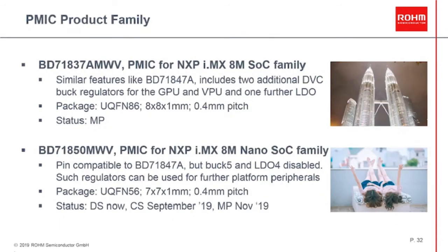Before ending the presentation, I would like to take the opportunity in mentioning two PMIC family products. First is the BD71837A, which addresses the i.MX 8M SoC family. This product is already in mass production, comes in an 8x8 QFN package, and includes two additional bucks and a further LDO. Second is a product which will be released soon and addresses the i.MX 8M Nano SoC family. This BD71850 is pin compatible to the presented PMIC, means comes in the same package, but two power supplies can be used for further platform similar to LDO4 of the BD71847.